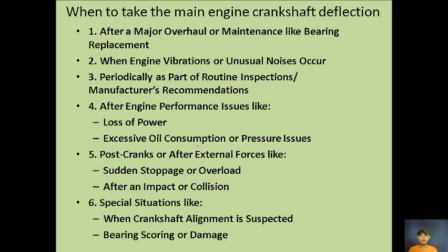Okay, so let's go. When to take the main engine crankshaft deflection? First, after a major overhaul or maintenance like bearing replacement. Second, when engine vibrations or unusual noises occur. Third, periodically as part of routine inspections or the manufacturer's recommendation. Fourth, after engine performance issues like loss of power, excessive oil consumption, or pressure issues. So you should always check your crankshaft deflection.